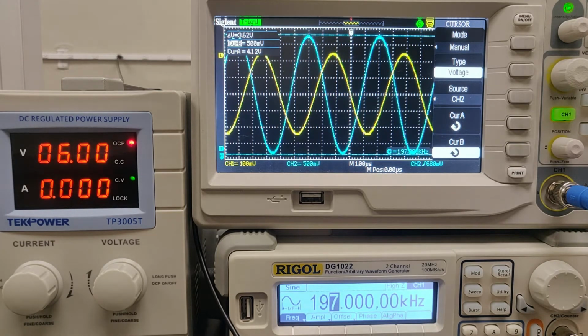our gain for our open loop system is very large. It's a huge number. And so we're not just going to be substituting one equation into another equation and solving for our V out over Vn. We have to make an approximation. And the important factor is that in equation 1, A is a very large number.